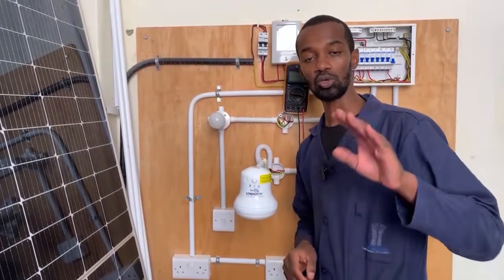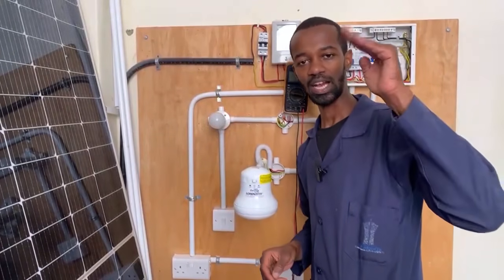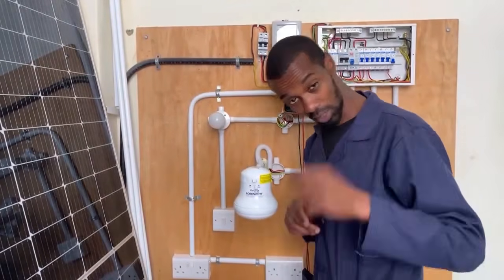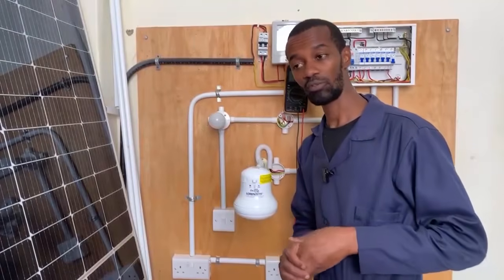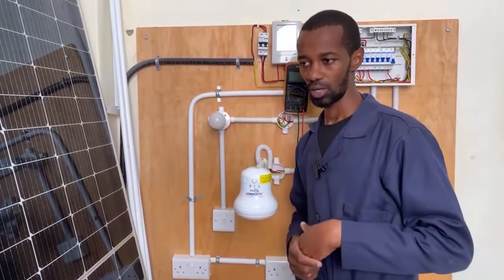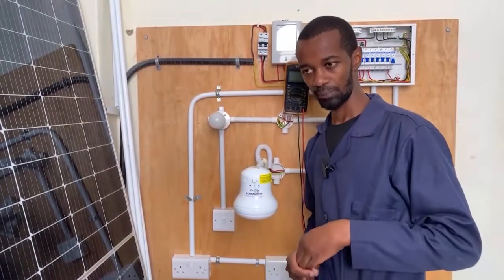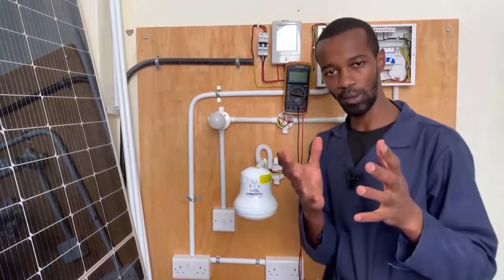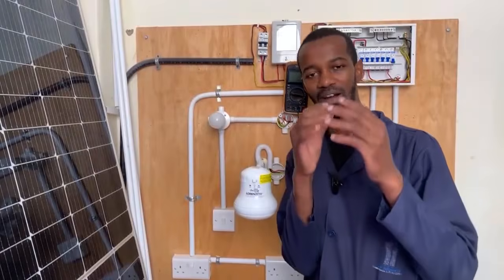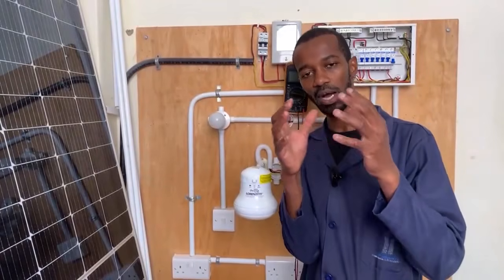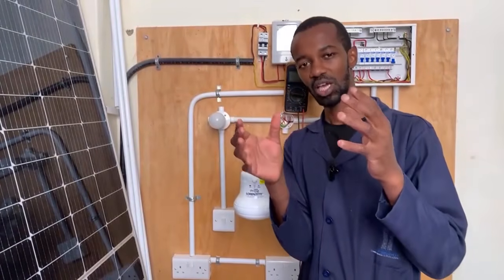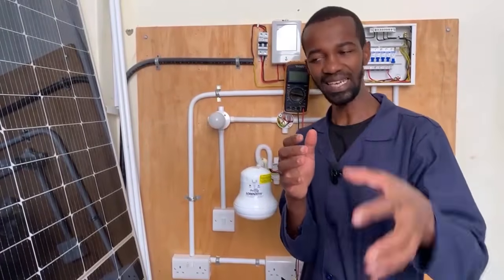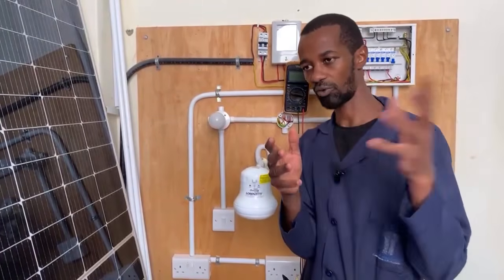So what you do, you go to the next higher level. Assuming your digital multimeter has a 20 like mine, if you want to record DC, which is 12 volts, you don't place it at exactly 12 volts. You place it at 20 volts, so that if at all you get anything above 12 volts, your digital multimeter is not damaged. You're not using the digital multimeter for that day's purpose only. You require it for more days.